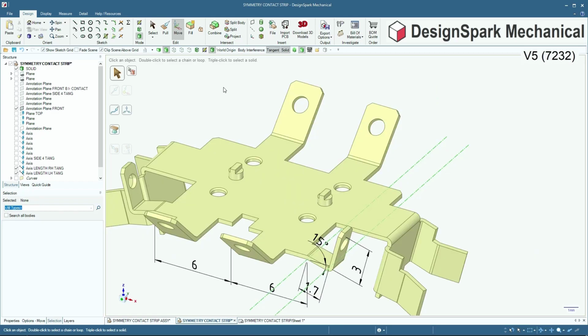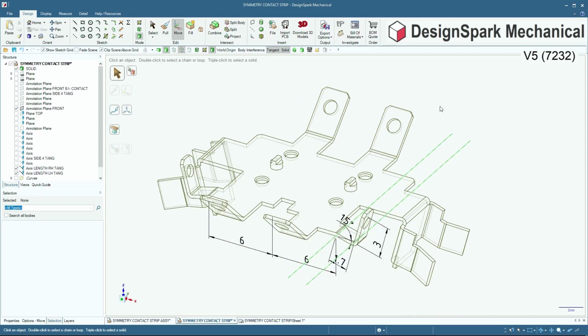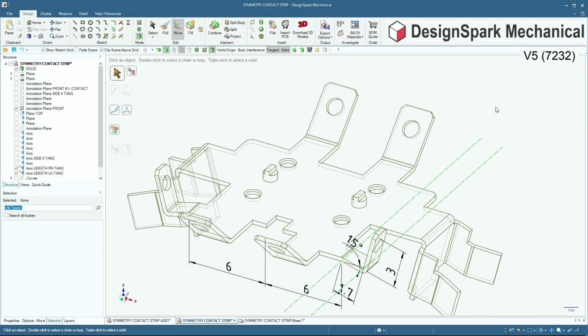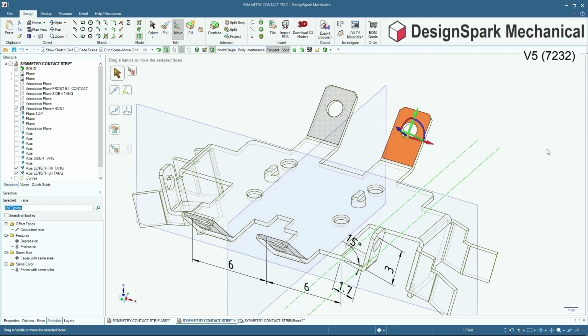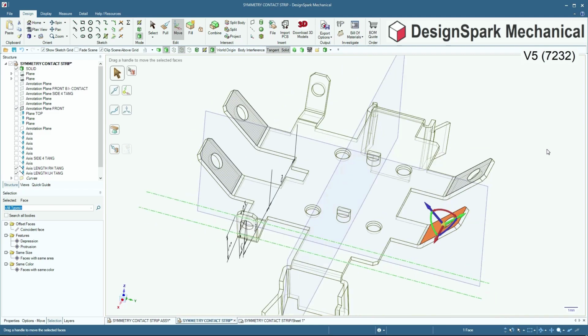Once created, these relationships, these linked face associations, are owned by the body as in a feature symmetry situation, or, in the case of a handed body pair, by the owning body's component. There's no structure browser mirror icons to interact with, but by just mouse hovering over a face, linked faces texture highlight, and upon selection, the corresponding mirror plane is displayed. So this is a very visual way to confirm a modification change and get a quick result.